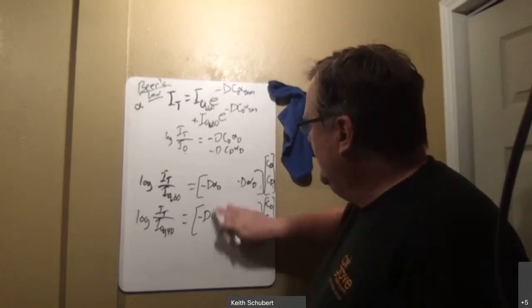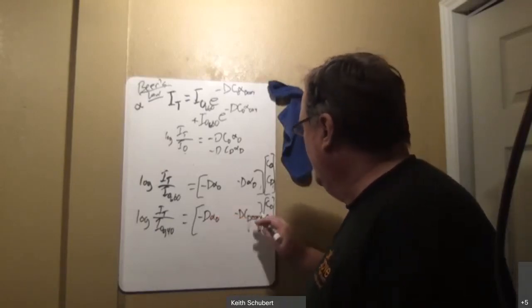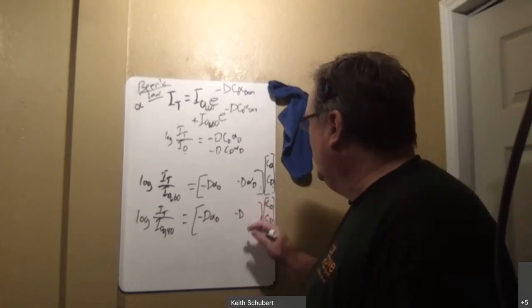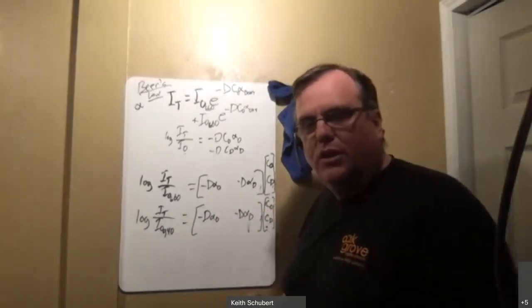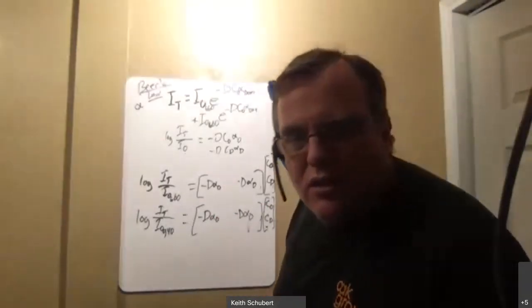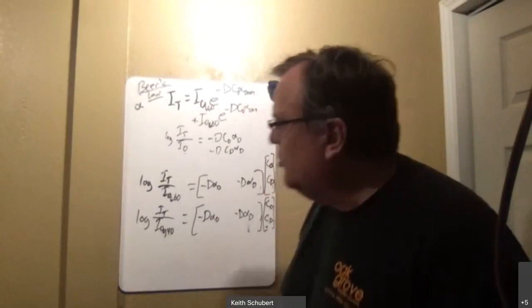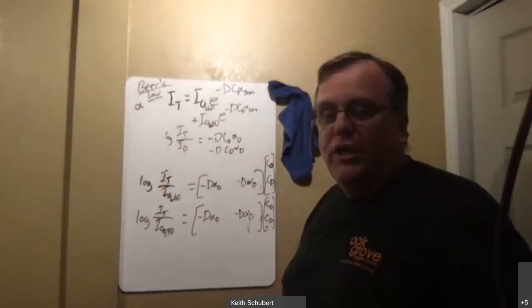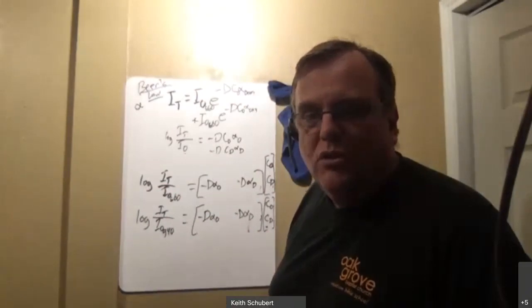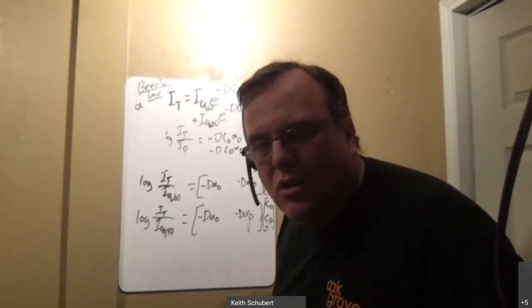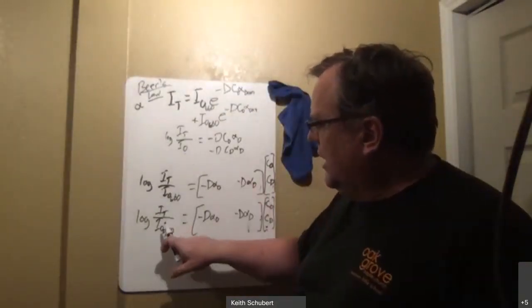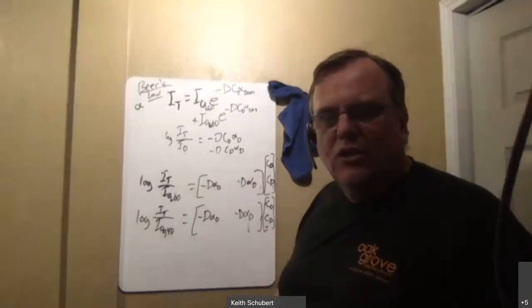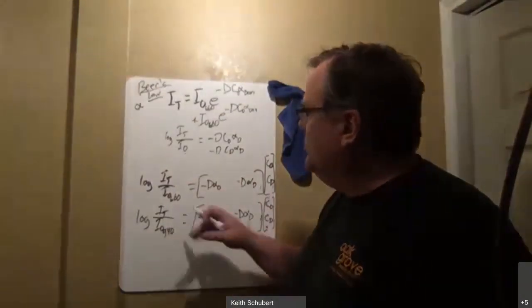Concentration deoxy. And the reason why I want to rewrite them is once I go to try to actually do a NIRS or to try to do a pulse oximetry measurement, it doesn't matter, we're doing log and stuff. So when I'm writing log here, remember all logs are equivalent. So my statement was I'm picking, I was doing 660 and 940, I think. But it doesn't matter. You can pick any ones along the line.